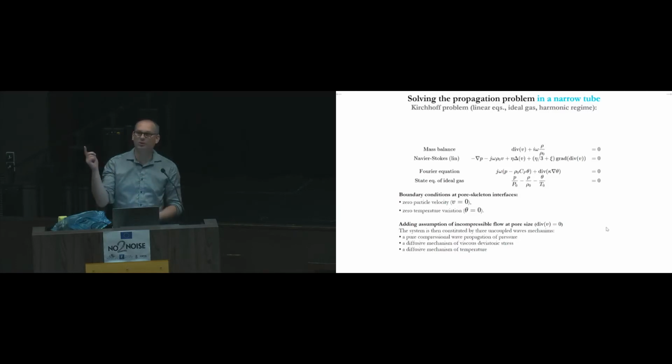So you remember this particle moving? At the scale of a particle, you can say that the flow is compressible. But if you look at some of the particles, you can see that we can almost say that the fluid is incompressible if I look at a larger scale. If you do so, you have a condition which is div of the velocity equal to 0.